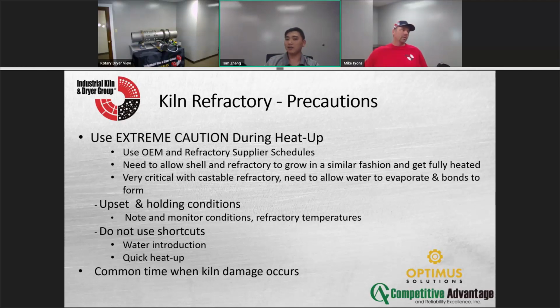If you cool it too quick, the refractory won't grow or contract at the same rate, and then you'll have a whole bunch of refractory breaking apart. That's why in the kiln you have the cooling process and the warm-up process: 24, 48 hours. Right. It's longer.